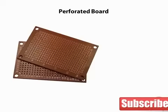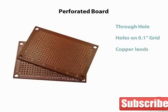Perf boards are a step up from breadboards. They allow us to insert components through holes, usually spaced 0.1 inches apart. The leads can then be bent over on the other side and connections made by soldering leads and jumpers together. Some perf boards have copper traces on them that you can use as a pseudo-printed circuit board. Perf boards are better suited to through-hole components, but there are some specialty perf boards that have surface mount footprints on them for surface mount components, as well as holes for through-hole components.